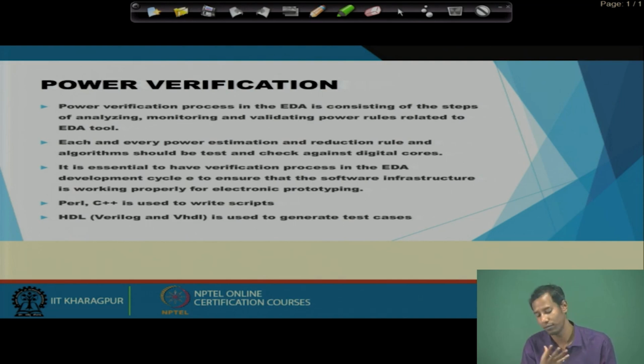Whenever I get all the switching activity information, I store it somewhere, and then if I give that switching activity to the tool, only then can it calculate, based on these switching activities, or based on this particular simulation, that means based on these test vectors, that this is the activity, and this is your power report of dynamic power consumption, leakage power consumption, switching power consumption, or glitch power consumption.